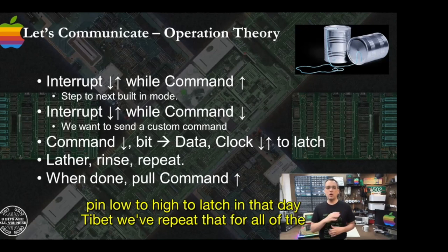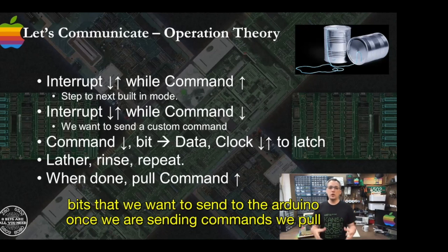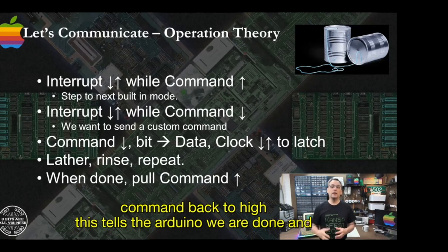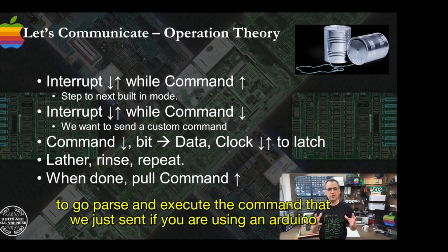We repeat that for all of the bits that we want to send to the Arduino. Once we are sending commands, we pull command back to high. This tells the Arduino we are done and to go parse and execute the command that we just sent.